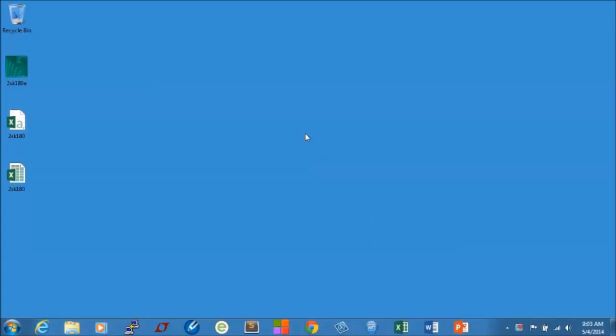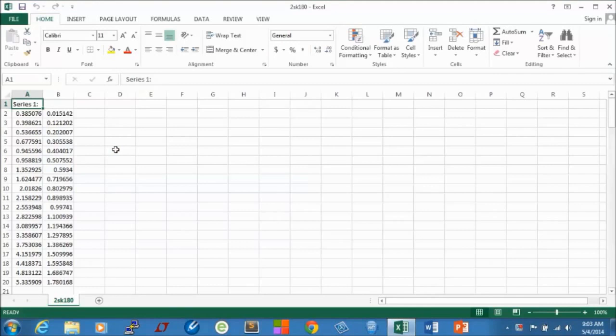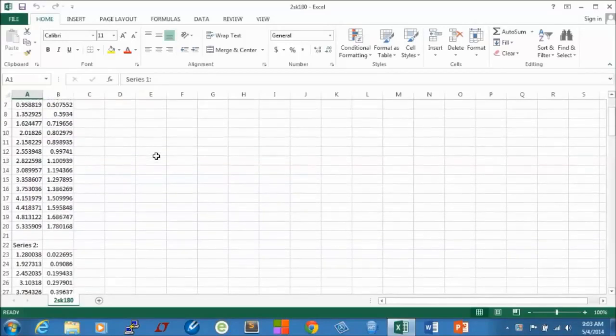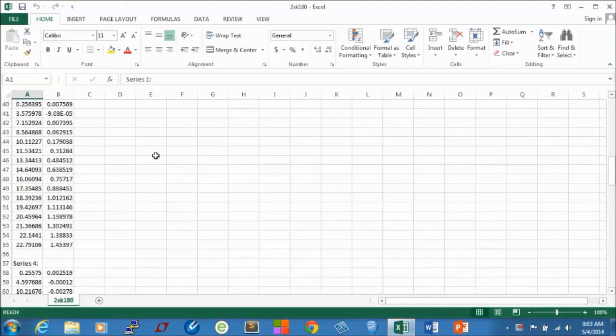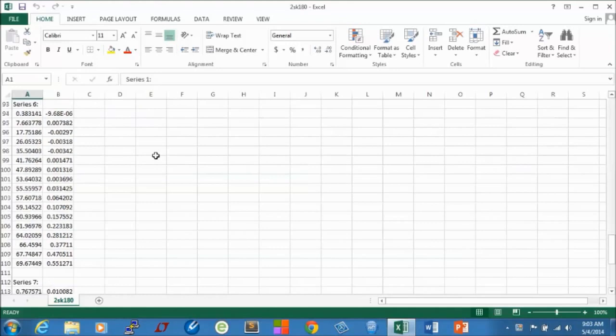Okay, so now we have some numerical data, and we're ready to do some curve fitting using Microsoft Excel and the Solver add-in. I'd like to thank Jack in New Jersey from techdiy.com for posting information on how to do this for vacuum tubes, and all I've done is just extend the concept to SITs. This is what the data file looks like from GraphGrabber, and you can see each series is just XY plot data for one of those traces.